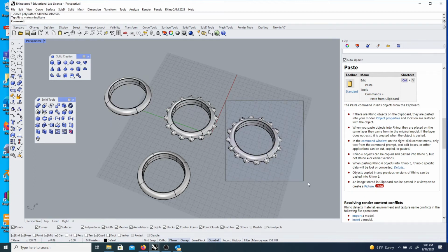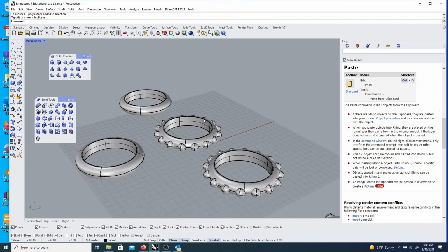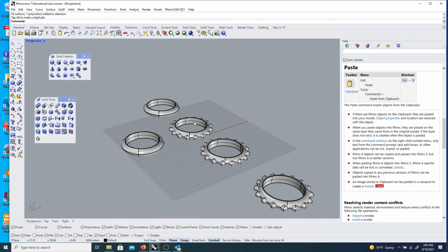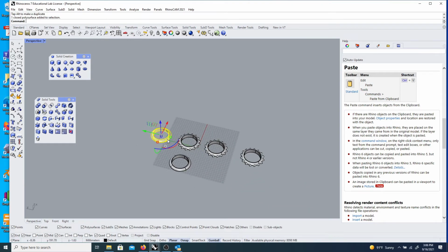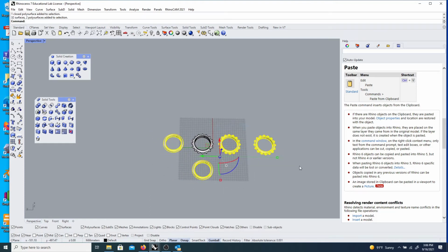So if I want to select all this stuff, I can drag it out, tap the Alt key, and that makes a copy. So it's good to have multiple working stages of your stuff. And if I want to be like, okay, this stuff is all great, but I want to put it on a different layer just to get it out of my way.